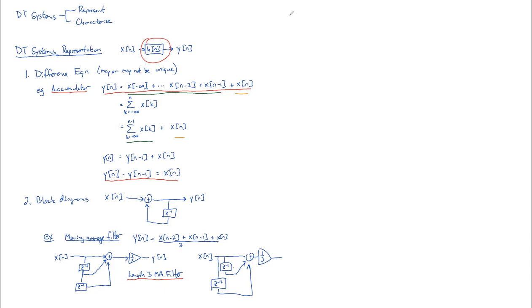Let me show you when you'd actually use a moving average filter, another example of it. Sir, what does the delay do? The delay, you'll remember from one of our earlier lectures, if you plug in x of n into a delay, what you get out is going to be x of n minus 1. So if you plug in a stem like that into a delay, where it's all zeros before, what you get out is, here's your 0 element, and now 1, 2, 3. So it's the same thing as you put in, just delayed by 1.